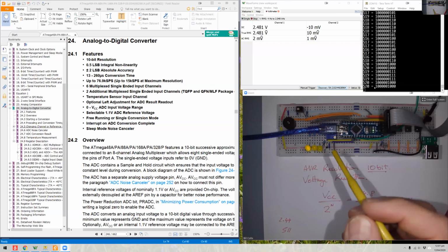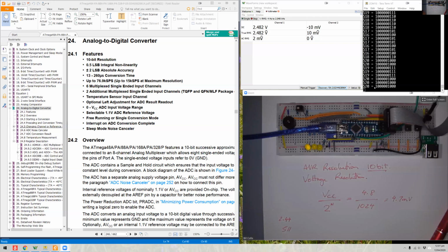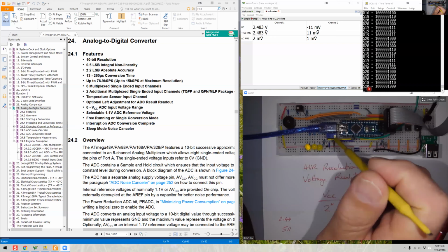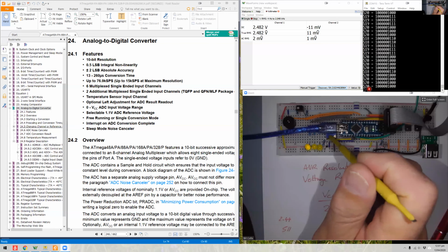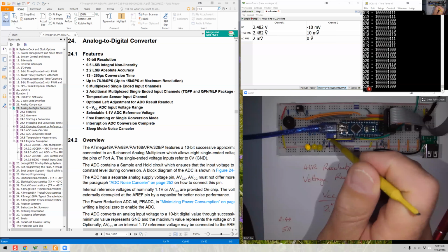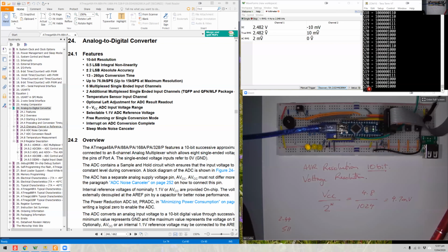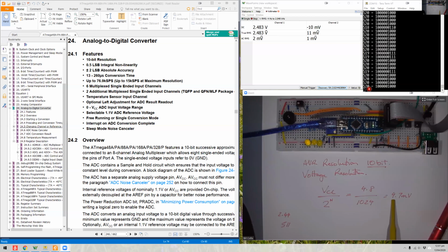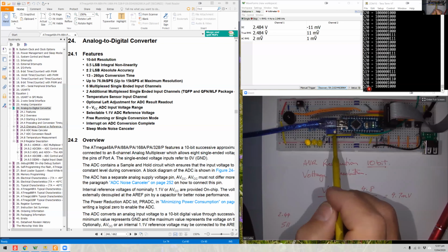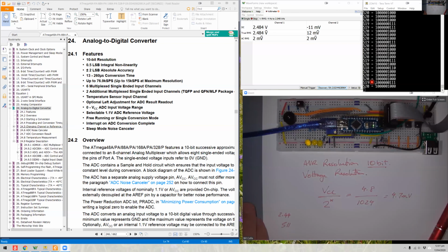You know, we really don't have the accuracy. Looking up here in our voltmeter, you can see that we're jumping around just a little bit. And also here, we're on the cusp of changes all the time. It's really hard with this cheap potentiometer, and the reason is that inside these is a very simple little mechanism which has got a lot of play or backlash in it. So what we can say, though, at the moment is we've got about 5 millivolts voltage resolution. For every change of 5 millivolts on our input, we're going to take another bit step in the output.